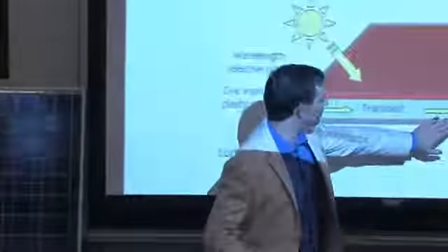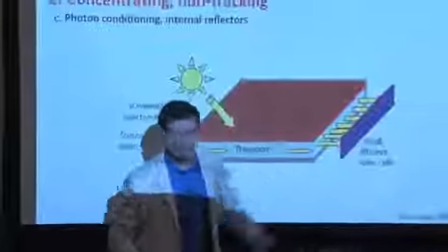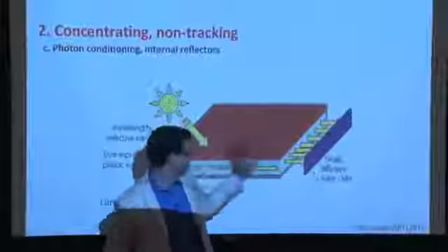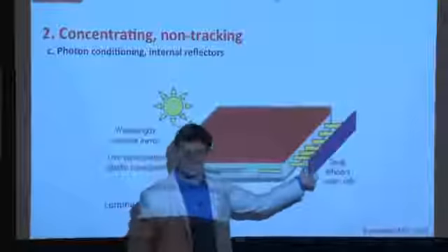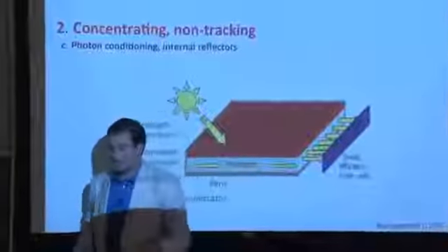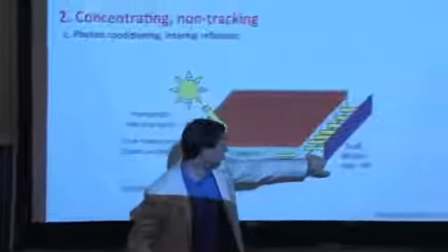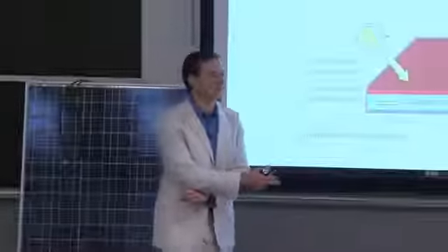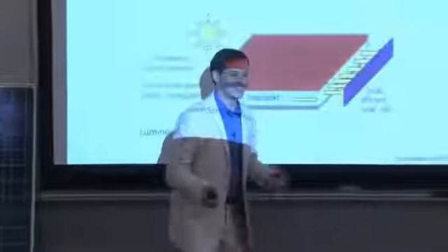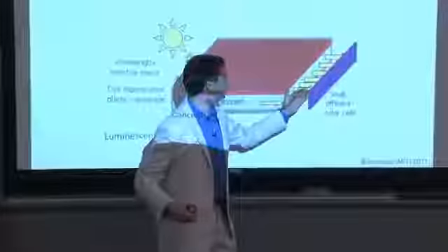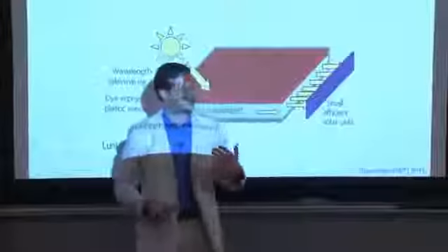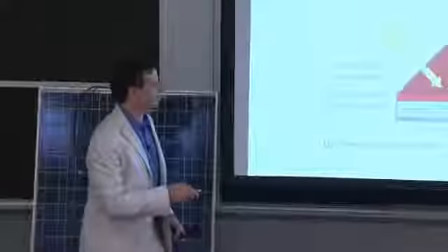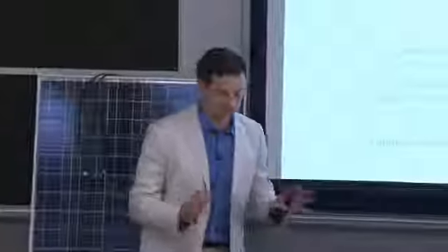So you can imagine a window that absorbs some of the incoming light, bounces the light off, and eventually concentrates the light in the corners where you have your solar cell devices. The advantage, or the potential advantage here, is that you can have a very high efficiency, expensive device, but a very small area of it. Instead of covering this entire area right here, you've now reduced the total area. And then, if this is a very small percentage of the total system cost, you can just switch it right out when a new and better technology comes along. Almost like you switch out your computer, right? So if a better solar cell device comes along, you can take this one out and put the next one in. It's almost like an upgradable system, because the majority of the embedded cost is in the concentrator and not the solar cell device itself.